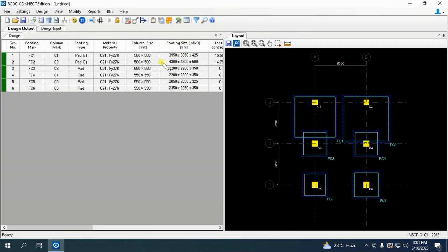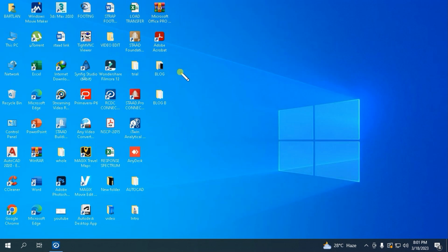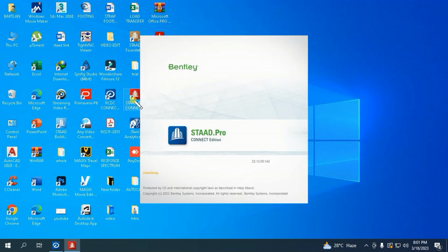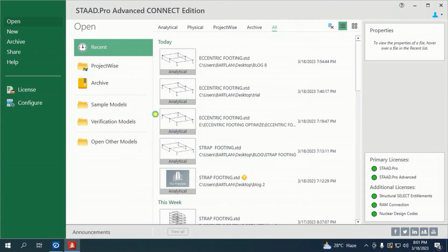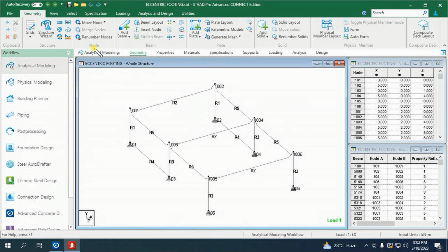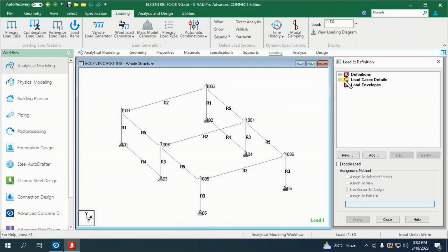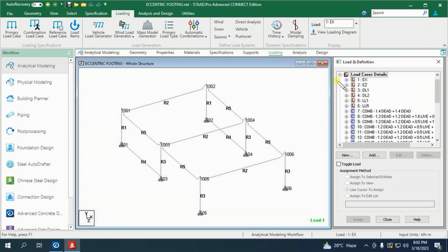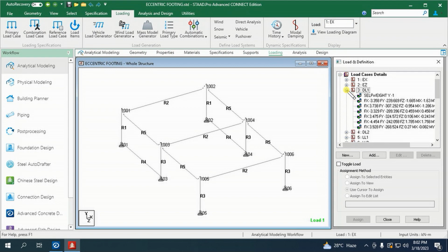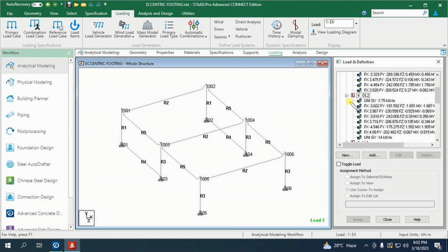As we can see here, the eccentric footings are far bigger than the rest of the footings. To make all of them almost equal in size to the rest, we will apply a moment to the base of the two columns with eccentric footings. Applying a moment in that location will force the grid beams connected at the other end of the column to react together with the strap beams. Hence, the load is redistributed among members like beams and columns.